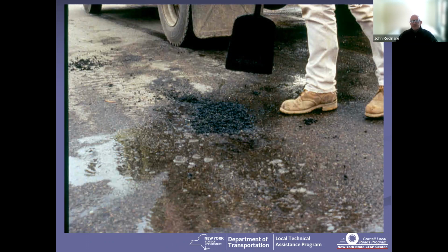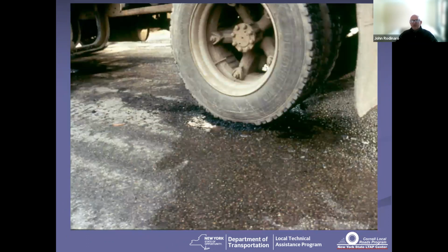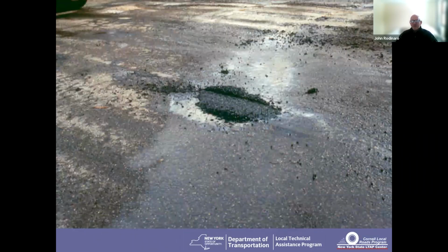But then here's the key. You back up with your truck tire, you hit it, get that nice and compacted, and that's critical, because the force of those high pressure tires is squeezing that material together, and that force is activating the polymers in that mix. So that stuff is like super glue now. Then you pull back forward, and you've got your finished pothole. The only thing I'd do differently here is hit it one more time with one more back and forth, get down, knock off those edges. But you've got a filled pothole that's going to last you for the rest of the season.